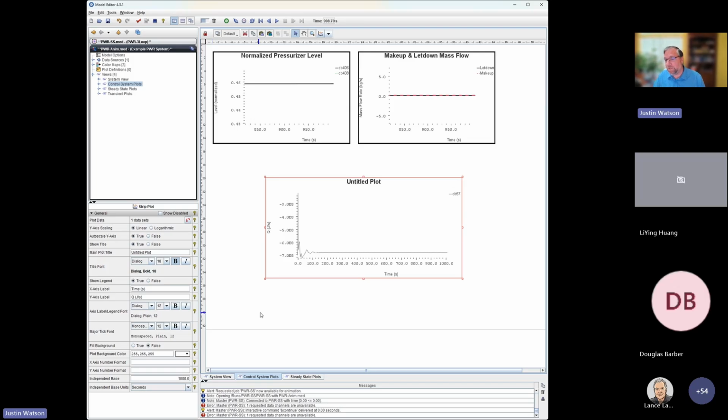One thing you can do is that the energy extracted from the steam generators should equal the total power being input to the system. So you can simply create a new control system or control procedure for each of the steam generators, add them together, and compare that value to the total energy input. And that's sort of what the follow-on exercise tells you to do.